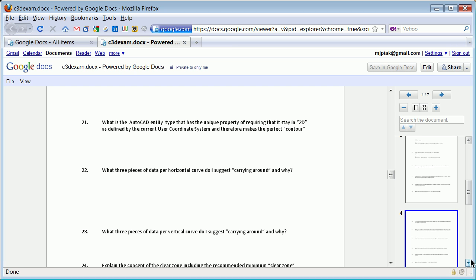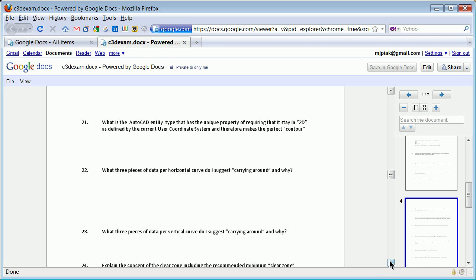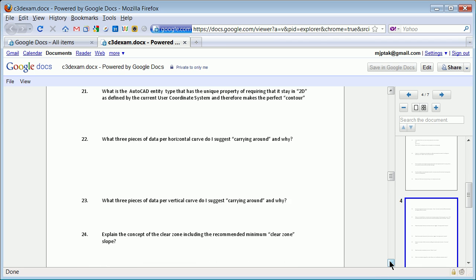For a vertical curve, station, elevation, and either the k value or the length of curve. You have other values, r and the like. Almost every subdivision ordinance will talk about k's. You should learn the relationship between the different ones, but in Civil3D it comes up and asks for a k or a length of curve.